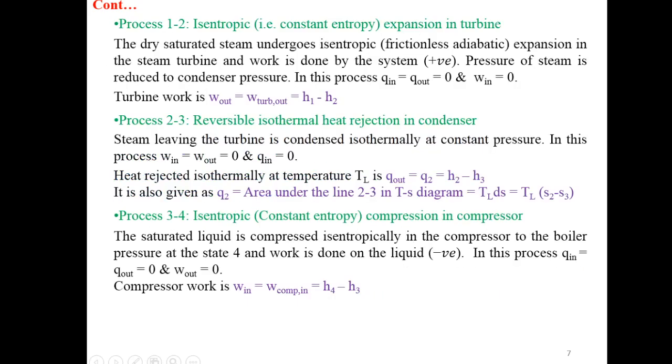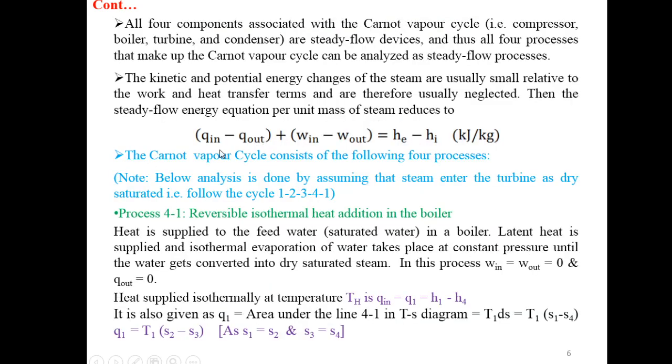So if you apply that condition in this equation, then what we will have? Q in 0, W in 0, W out 0, exit point is 3, H3 minus H2, it will be equal to minus Q out.